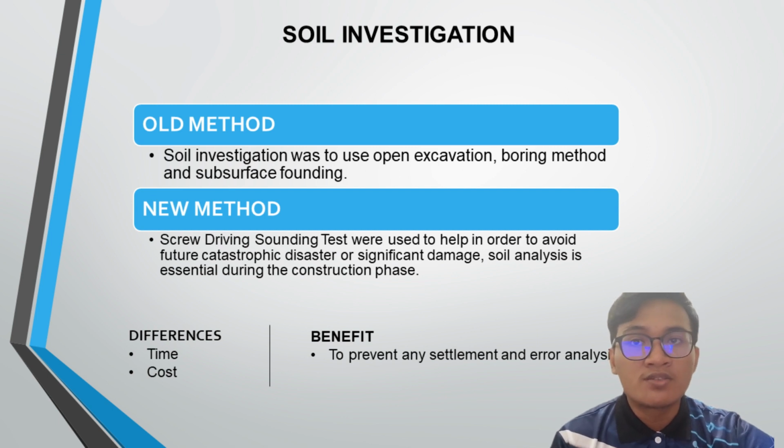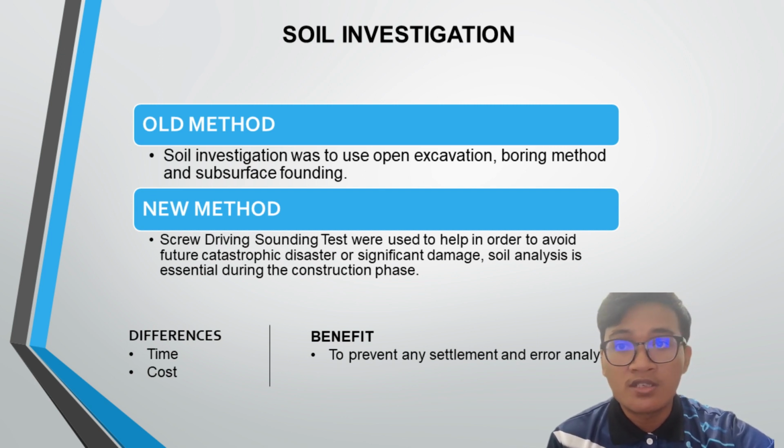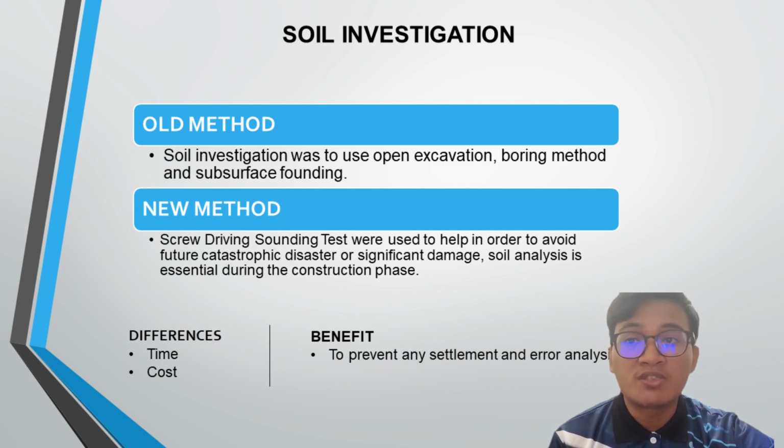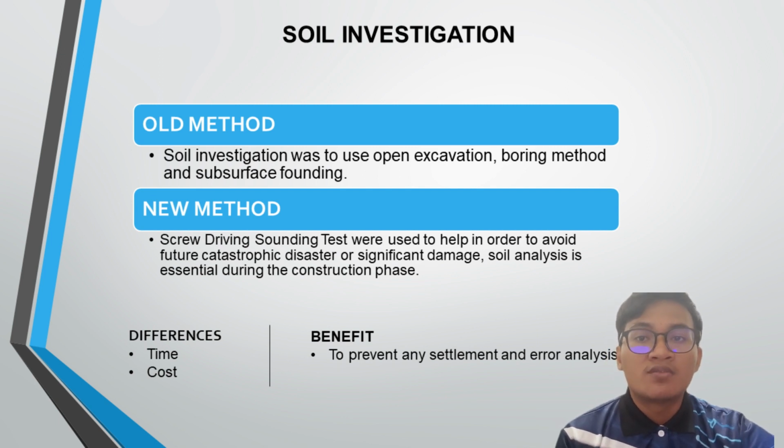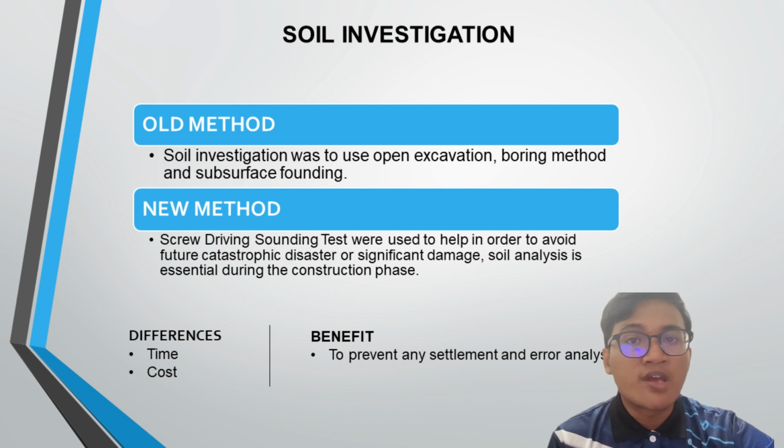The old method uses open excavation, boring method, and subsurface soil sounding. Then the new method uses screw driving sounding tests to help avoid future catastrophic disaster or significant damage. Soil analysis is essential during the construction phase, and the difference is in time and cost. The benefit of this method is to prevent unsettlement and errors in analysis.